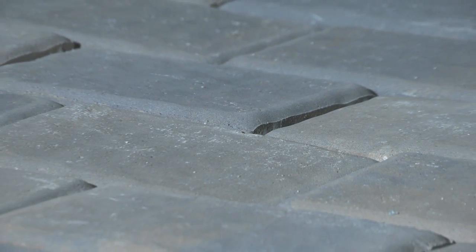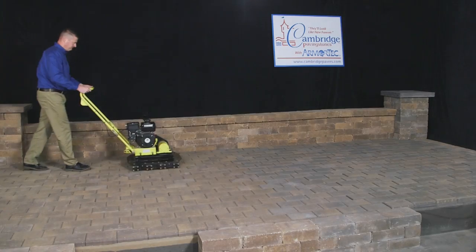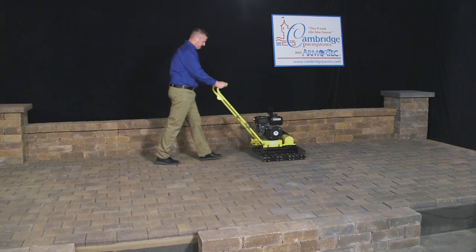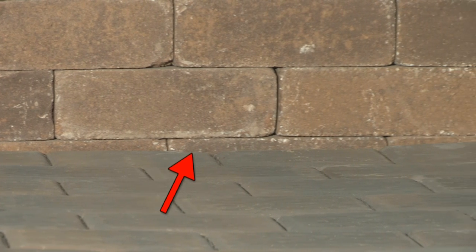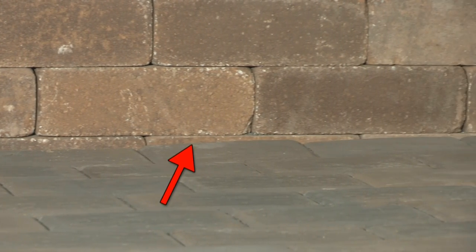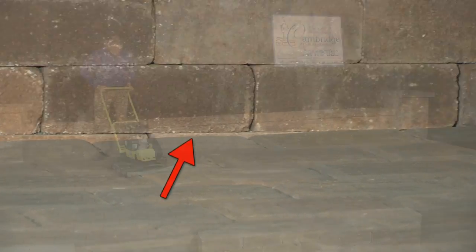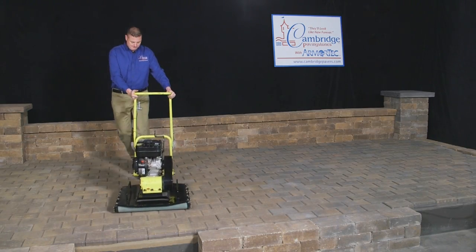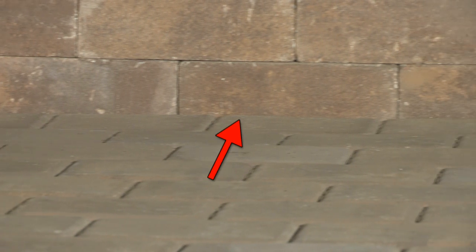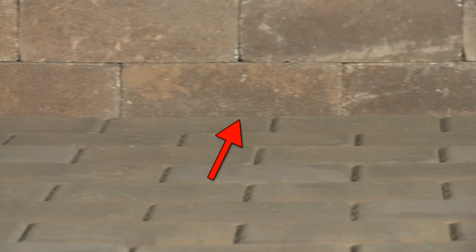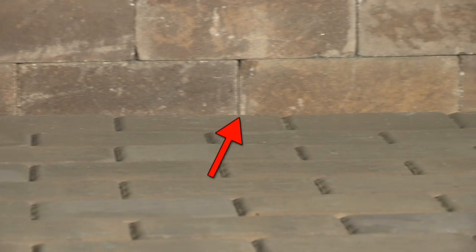First, there are specifications when producing paving stones that manufacturers have to follow. One of these is for height tolerance. The acceptable variance for the height of a manufactured paving stone is plus or minus 1/8 of an inch. We've all been on a job site where there are some different heights in the paving stones. When that product is installed on a stone dust setting course, oftentimes you cannot achieve a level pavement surface because stone dust becomes rigid, not allowing a paver to be compacted into it. When installed on 1 inch of loosely screeded C33 sand, the final pavement surface will be level after compaction because the paver can be compacted into the sand, forcing the sand up into the joints.